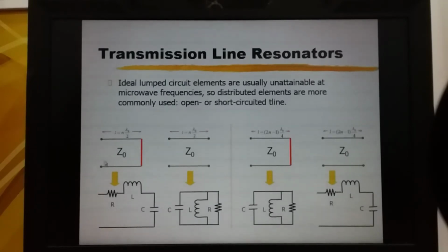In other words, we have a series resonance characteristic where the impedance is 0 ohm at exactly the resonant frequency, but it is capacitive or inductive at a frequency higher or lower than the resonant frequency. We can then represent a half wavelength transmission line shorted at the end with an equivalent circuit of a series LC network.